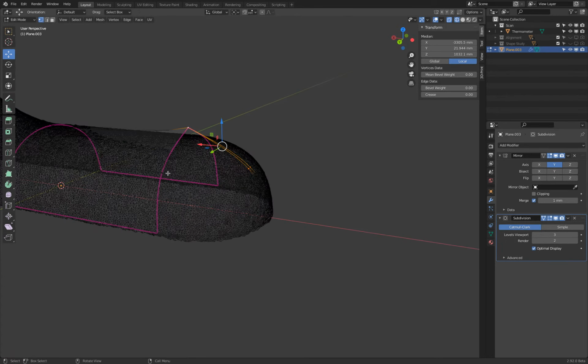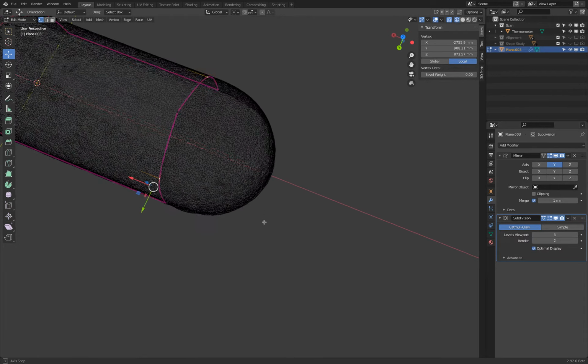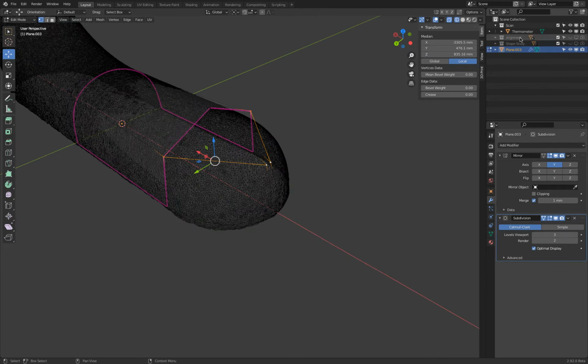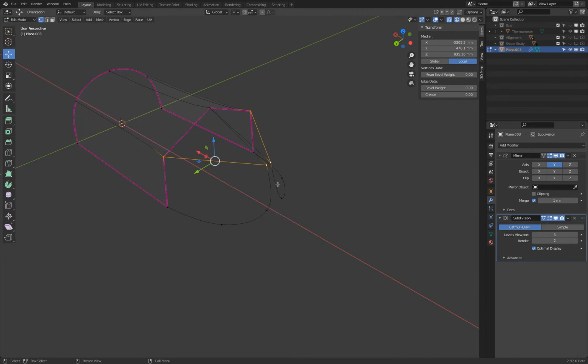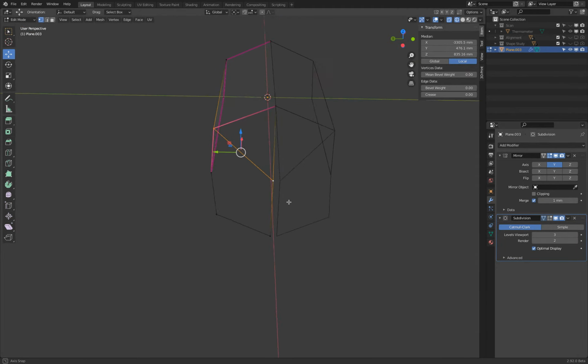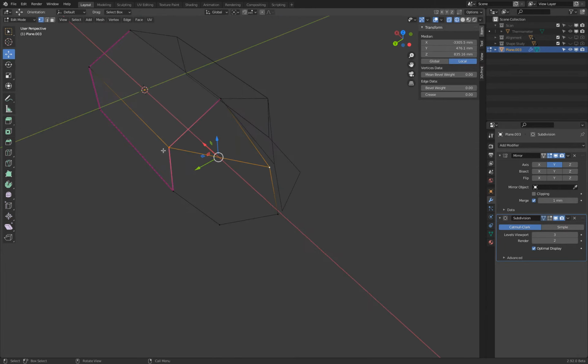Okay. That means an U, and here's this point. We can select and press F, and we filled it. Let's hide this one, because right now everything might otherwise be a little bit confusing to look at. So you see here how from here we extruded via E the line out, and then from here one time up, and then we connected this, and then these two we connected.